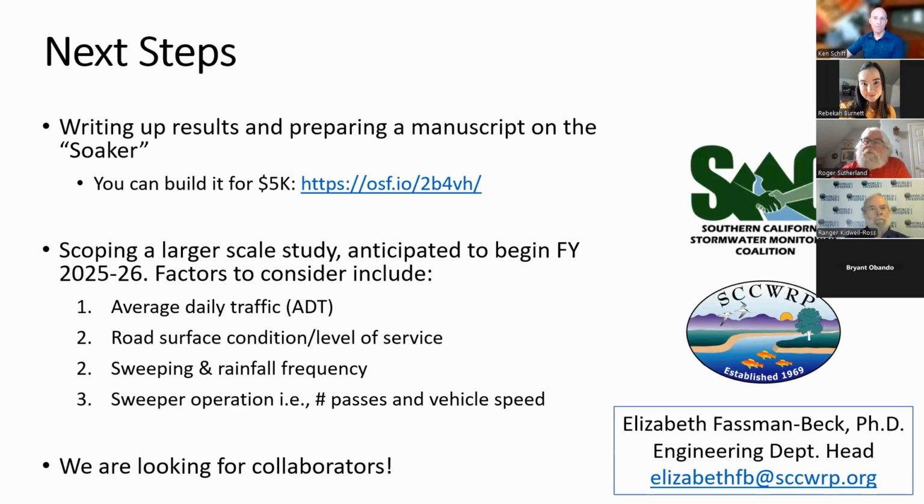I think when you think about accumulation, most of the accumulation in the real world is happening in gutters, and most of the gutters are concrete. The asphalt interface ends at that gutter lip. Sometimes that can create an opportunity for material to accumulate, making it difficult for the sweeper to get to, but much easier for the water quality flow to get to at the gutter flow. So I've never really seen any data of concrete versus asphalt. I don't think it's a huge difference maker. I think it's all about the wash off and the gutter flow aspect, which makes it much more complicated.